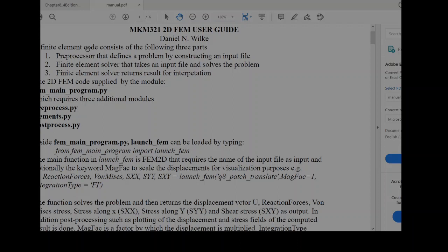This one in this course will be a normal text file that you can open up with WordPad or Notepad, just a normal ASCII file. So all that means is it's just text, in a sort of Notepad environment. The file type that we'll use here is always .inp, for input. These input files actually work in Calculix, so the files here should run also just as is in Calculix. Okay, so that's essentially the one aspect. The preprocessor defines the problem, constructing an input file.